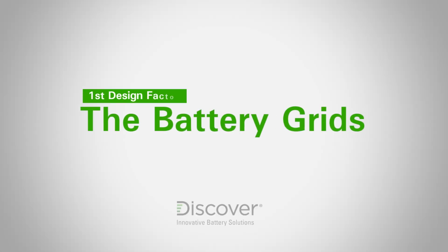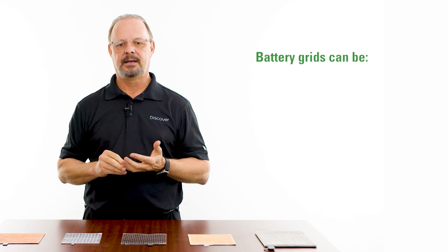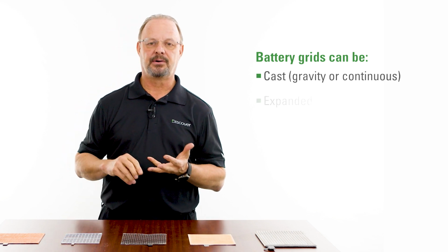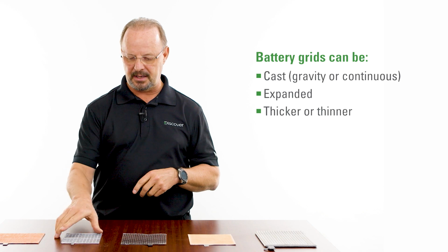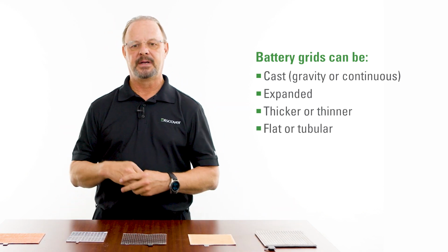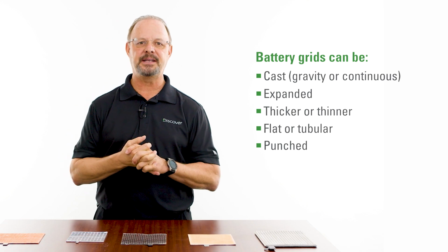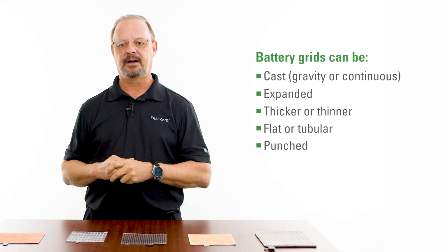So the first design factor that we're going to talk about today is the battery's grid. Like rebar in a concrete structure, a battery's grid provides the structural strength for what comes later. Battery grids can be cast or expanded, they can be thicker, they can be thinner, they can be flat, or they can be tubular. So there's many different ways to produce a grid to provide that structural strength to the